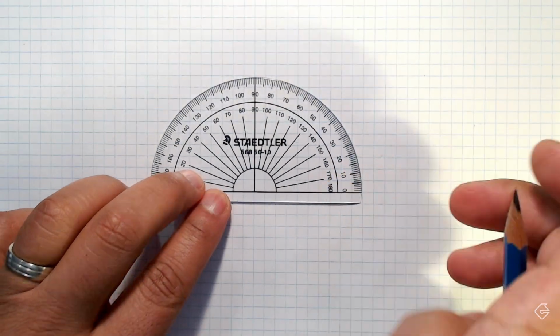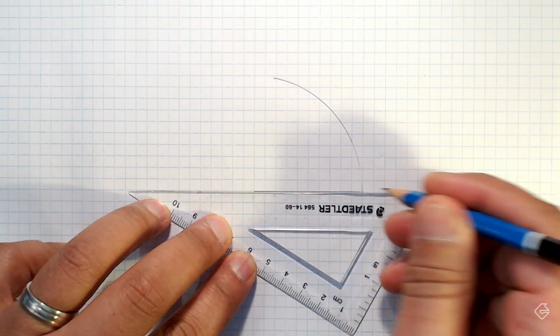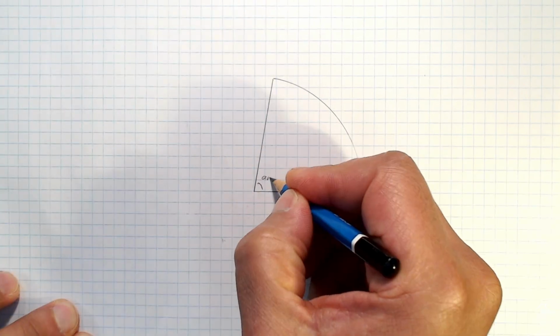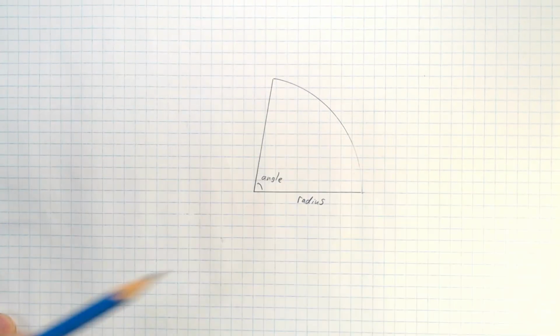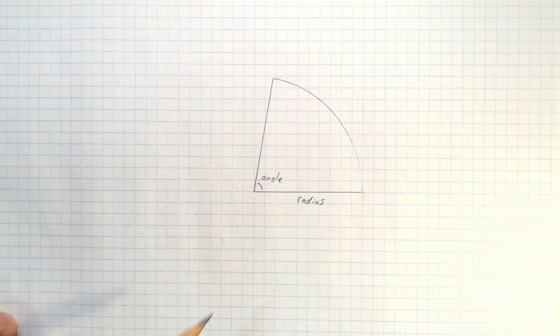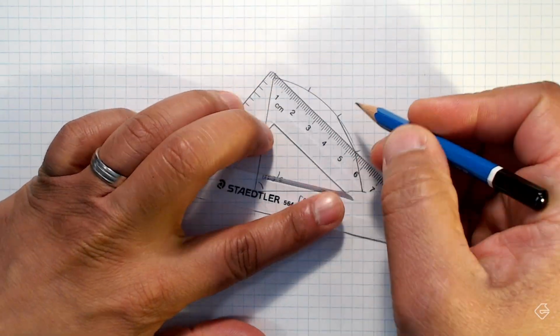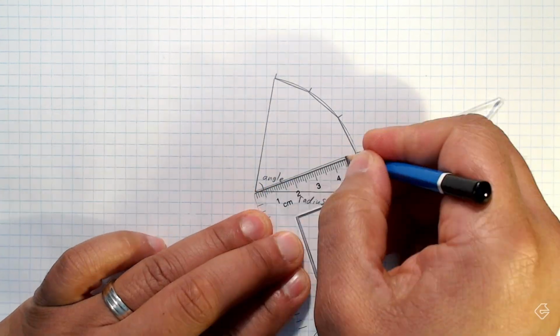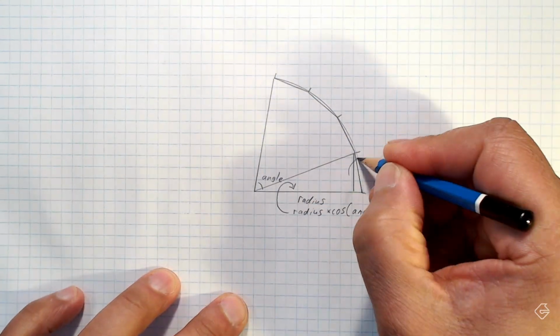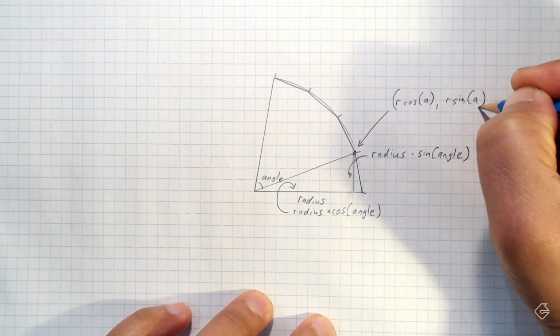Let's identify the basic components that make up an arc. Every arc will have a starting angle, an ending angle, and a radius. If we think about this curve as just a series of closely spaced points, well, we could use a for loop to create all of those points in the arc. And those points are basically connected by straight lines. That is, after all, how all curves in OpenSCAD are created. Basic trigonometry will give us the vector for each of those points. And we can stick that into a for loop like this.